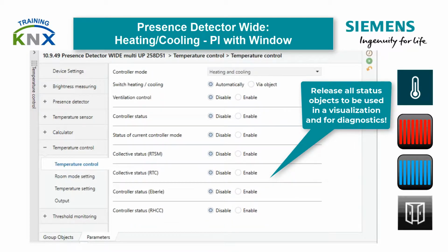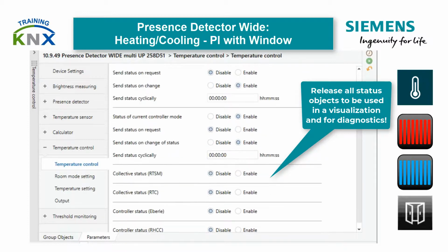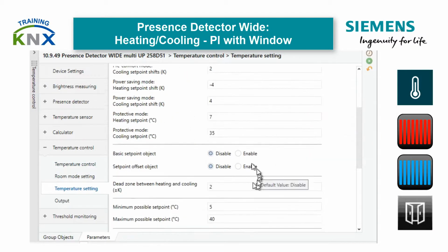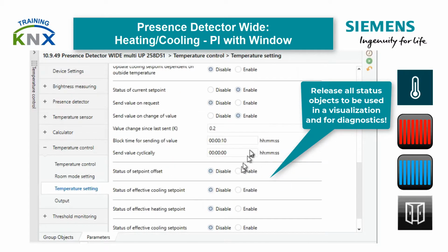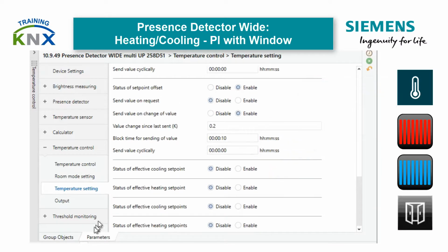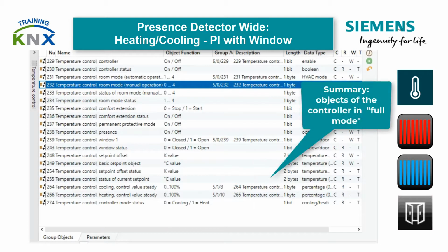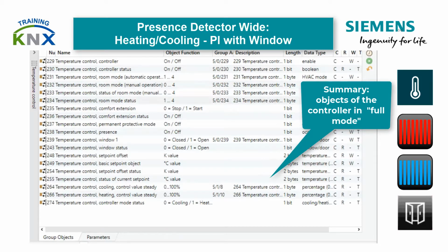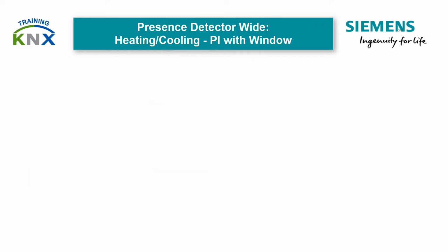To round off the configuration, it is recommended that you activate the various status objects and also connect the controller on-off object. The latter object is self-explanatory. The status objects provide current setting data for visualizations or displays, at the latest after a bus interruption. By the way, the controller on-off object is always initiated with 1. That means switched on after download or bus voltage return.